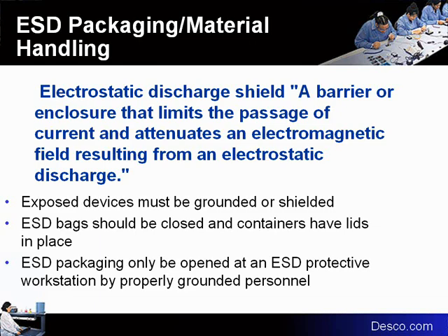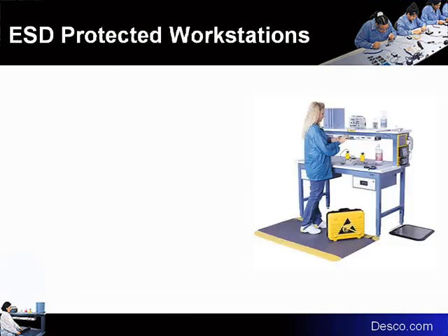The other dimension of shielding that is found is ESD garments, which has the same shielding effect for clothing. Clothing are insulators, and if they have a charge, it will not be reliably brought to ground via the wrist strap. So the ESD garment does a shielding factor for the operator's clothing.